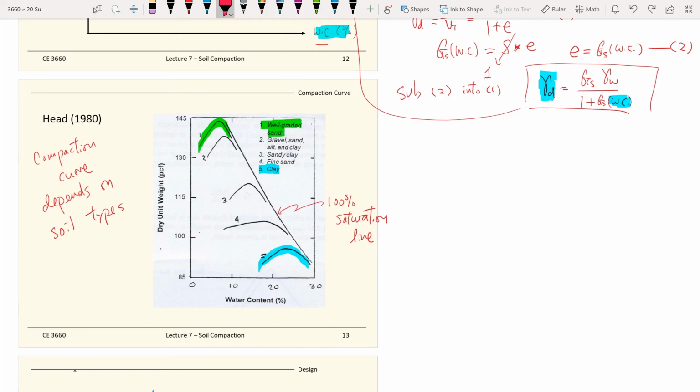So when it comes to density, when you want to achieve higher density, it makes sense to use well-graded material, where the small grains fill up the gaps between the larger grains when they pack together. That's why well-graded sand serves best when you want to achieve the maximum or highest density possible. So again, the compaction curve, or the anticipated compaction behavior, depends on the soil type too.